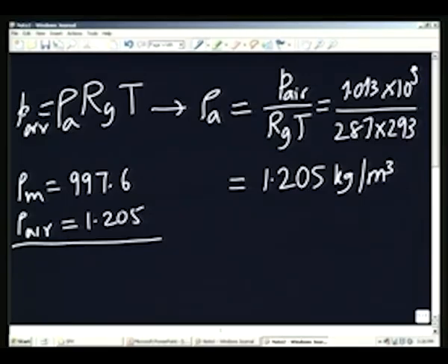The second part of the calculation requires two things. One is the area ratio. If you remember, the area ratio comes because we assume that the fluid, manometric fluid is incompressible. Therefore, to determine how much is the change in the height of the liquid within the well itself, we have to use the area ratio. This is how it comes to the picture.